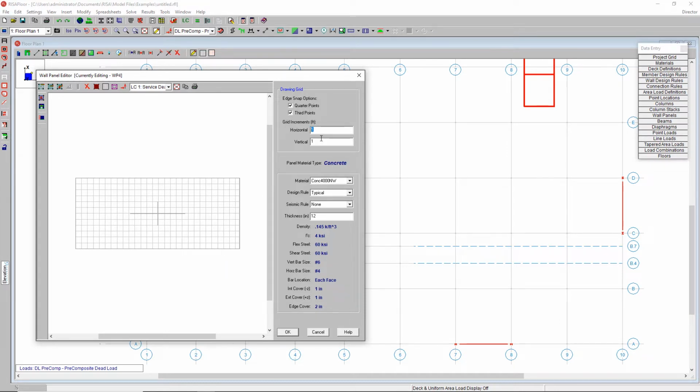So you can actually say, okay, I actually want to draw that maybe 19 feet in, 4, which means that the grid is going to have a different line up here. So this is at 19 feet from the edge there. So I can draw that in, and I'm going to just drop in a little opening. There we go. So you can see what that looks like underneath there. Internally, the program creates regions for these design regions. And so all of these walls will have a design region for reinforcement design.